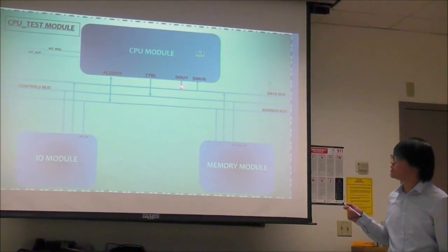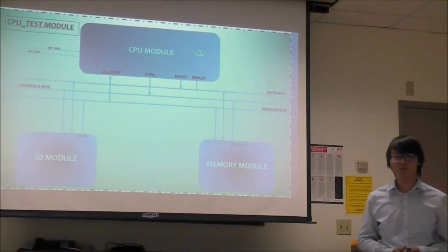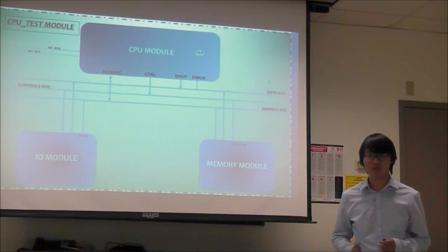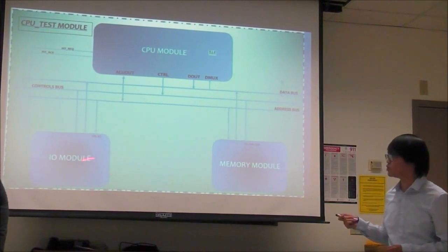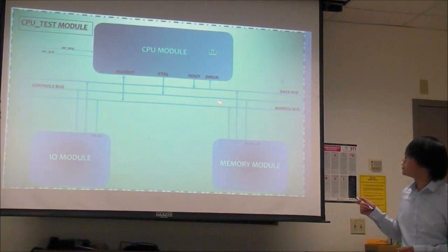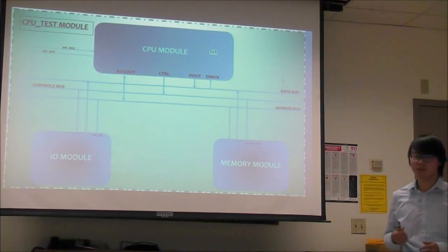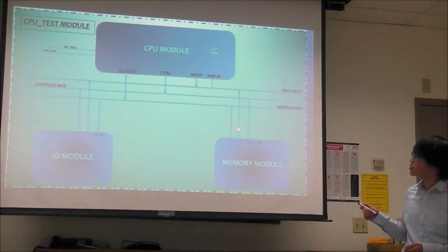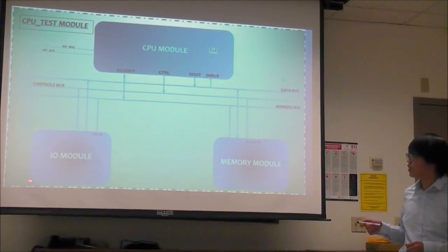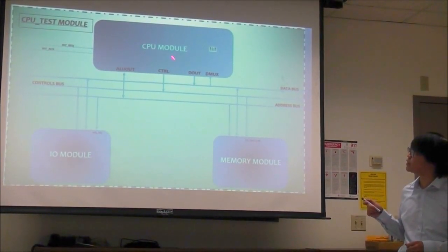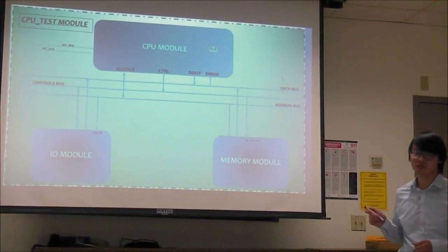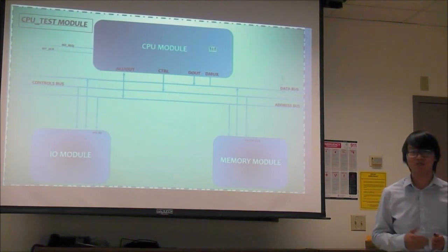It contains the D-out, which is the memory data that's being written into the memory modules. Our address bus, which comes from our ALU out, addresses which address we want to write into. And then our 2 memory modules can interact back with our CPU module through the DMUX, where it outputs the memory data.